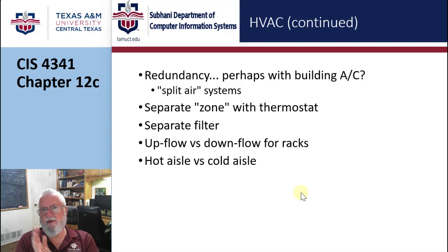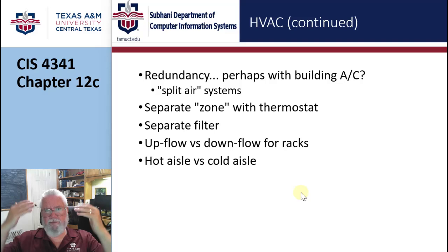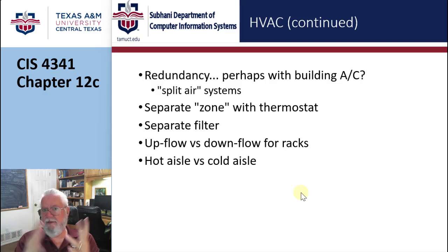Maybe you need one of those in-the-wall split systems, like in some hotels, where there's a thing on the exterior wall, a packaged unit that contains heat and air conditioning. It just blows stuff from the outside. But it would require a lot of ductwork, because I'm recommending you not put the room on the outside. But some sort of redundancy is involved, and clearly a separate zone.